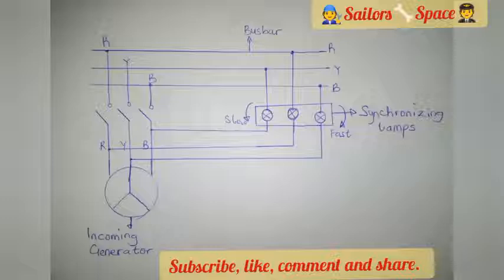So if this happens, you can resort to using what we call the synchronizing lamp. The synchronizing lamp is an alternative for us to use when we have total failure. Some people don't really understand what total failure means. They feel it is when you cannot use the synchroscope in the auto mode. No, when your synchroscope fails totally, you cannot use it in both the auto and the manual mode. So you resort to using the synchronizing lamp. It is more like a backup in the event of an emergency, such as the synchroscope going bad.